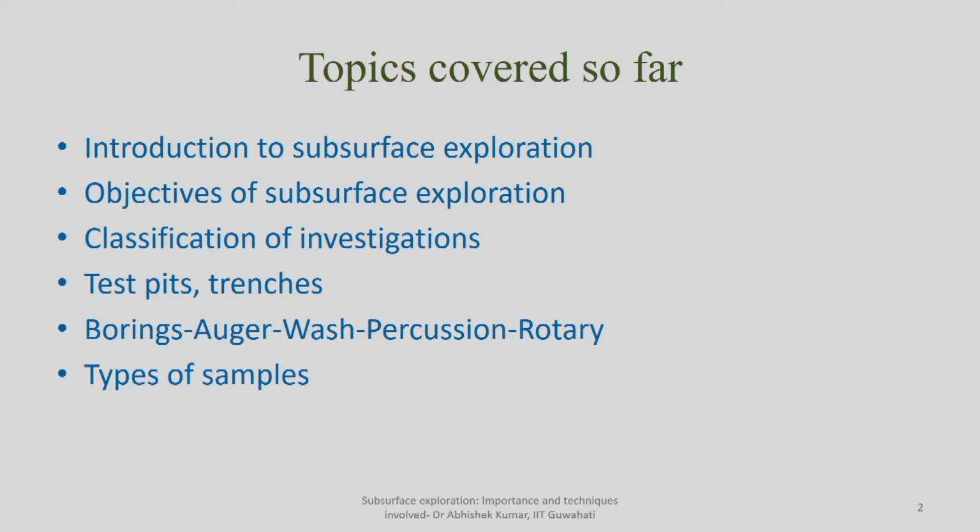So, that is the benefit of test pits and trenches, but the only limitation is we cannot go for deeper depths. Moreover, if the soil is collapsible in nature or cohesionless, we have to provide some kind of lateral support or bracing, which will ensure that during trenching at comparatively deeper depths, the soil will not fall into the trench. Then we discussed different kinds of borings, as I mentioned earlier also.